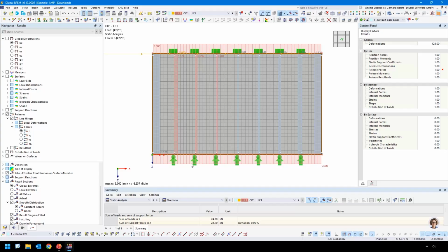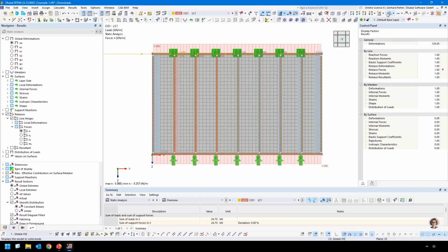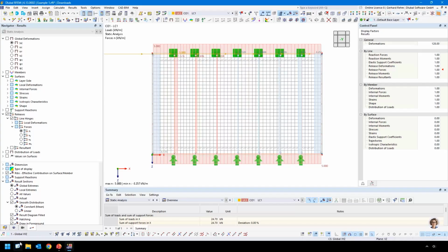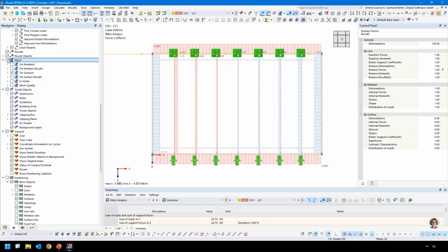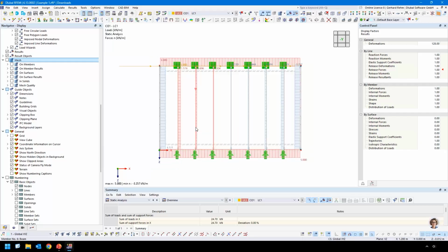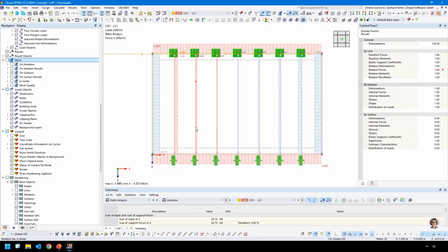So now we get exactly 5 kilonewton per meter at, maybe we can remove the image. Here we go. For the top and the bottom plate. But you see here on the edge, it's less, of course, because the vertical studs are covering some load as well. And the question now is if this is correct, and of course it is not correct in terms of timber